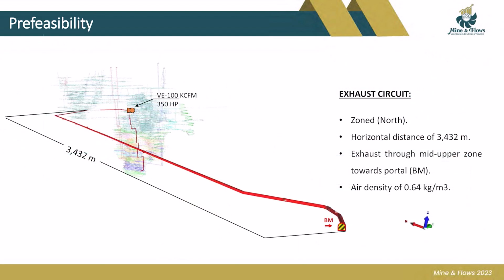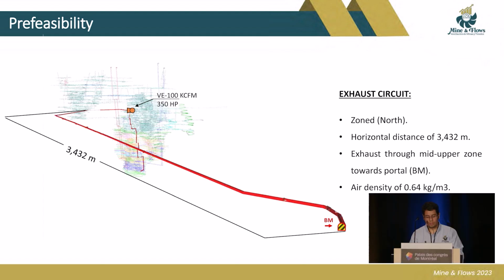Another identified opportunity for the improvement of the proposed design is the use of the access tunnel with the shortest distance to the production zone as an exhaust circuit. This alternative has two shortcomings. First, using a long distance and high resistance airway as an exhaust circuit is reflected in a high pressure and low airflow system.